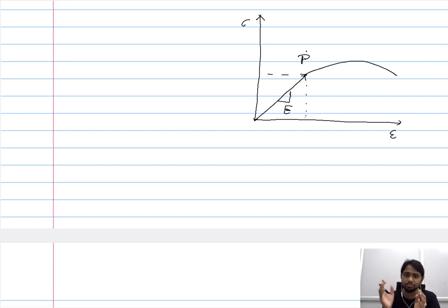And this can also be referred to as the elastic limit, because beyond this point the elastic deformation is accompanied by plastic deformation. You have a combination of elastic and plastic deformation beyond this point. So you have Young's modulus, you have the proportionality limit, or we can also refer to that as the elastic limit.